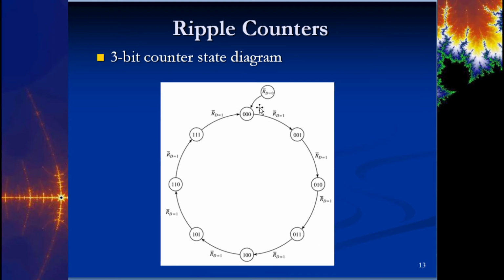But what happens if you're at 0 cents? There's 3 possibilities to get to the next state. You could put in a nickel, you could put in a dime, you could put in a quarter. So out of your 0 position, you'd have 3 separate paths. So what if you put in a nickel? Now you're at 5 cents. What are the options from there? You could put another nickel in and move over to the 10 cent state, you could put 10 cents in and get to 15, or you could put a quarter in and get to 30.